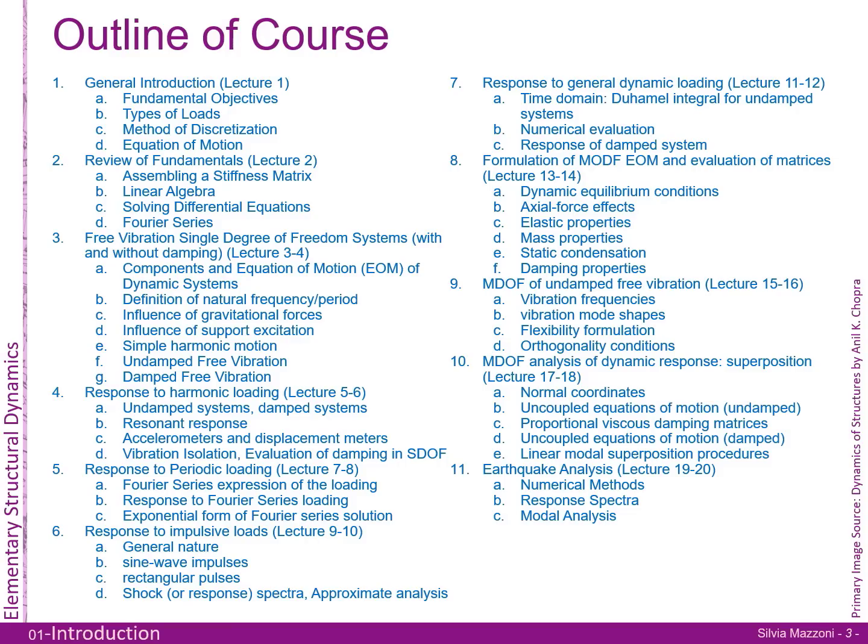Then, once we've really resolved setting up the equation of motion, we're going to look at how we solve the equation of motion, pulling out our toolbox that we've already developed for the single degree of freedom system. So we're going to look at the undamped free vibration of a multiple degree of freedom system. What does that represent numerically, but then also physically? So we're going to have to go into mode shapes and flexibility formulations and orthogonality conditions. Things there get a little tricky, but I think if we're prepared and comfortable, we can get through that part of the course as well.